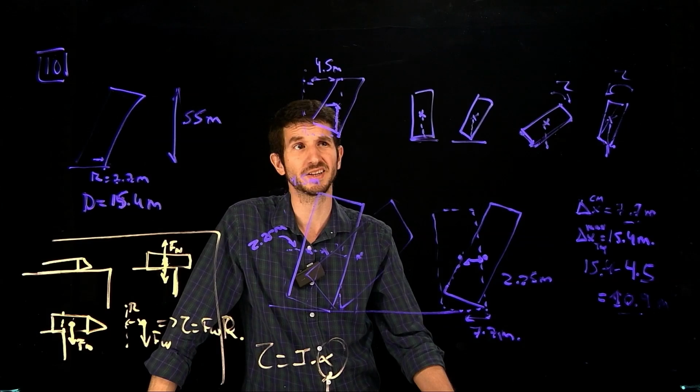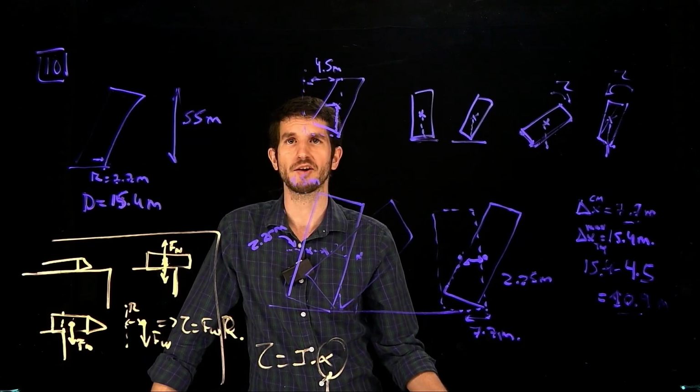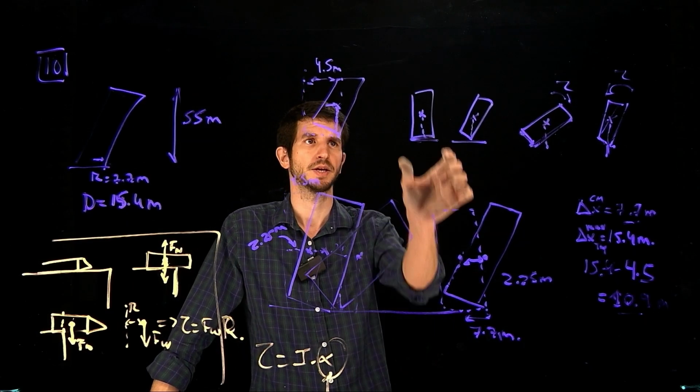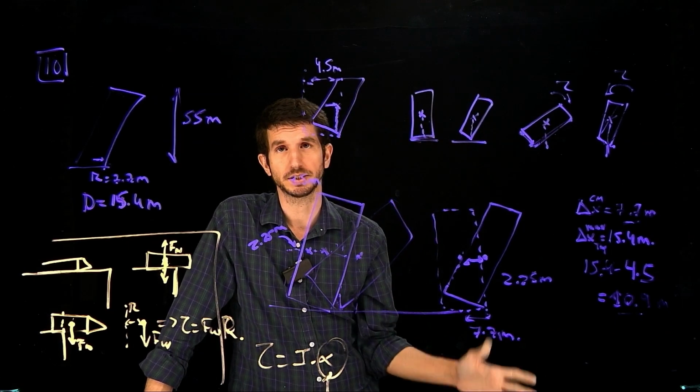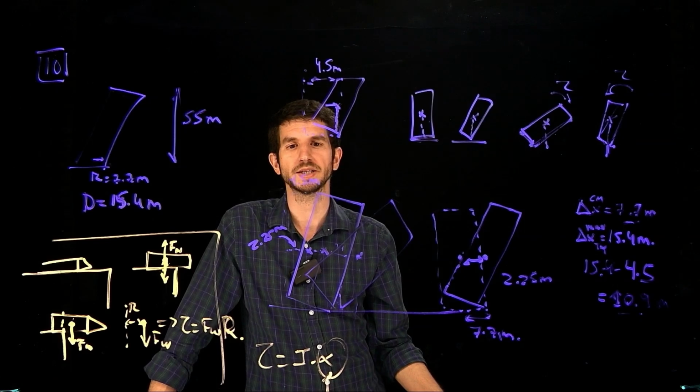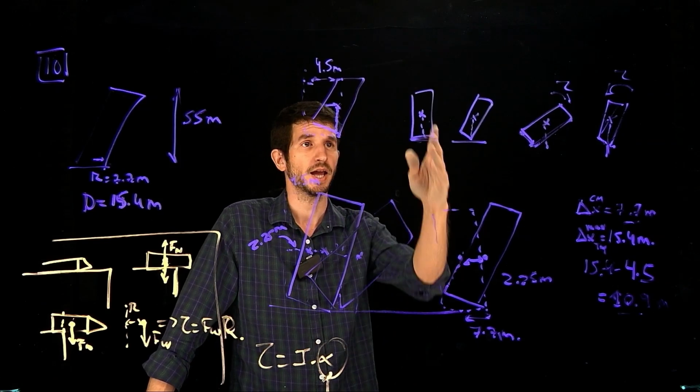Conceptually, we can apply it. Examples are going to be very simple. Whenever you have a problem of stability, make the diagram of the object, find the center of mass, which is going to be the geometrical center. Most of the cases we're assuming homogeneous masses. If not, maybe you have to think, and then see where does it fall.